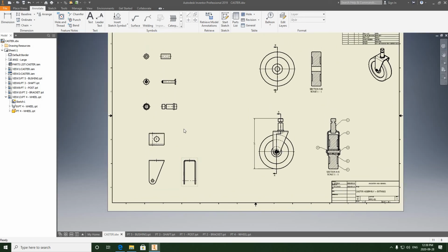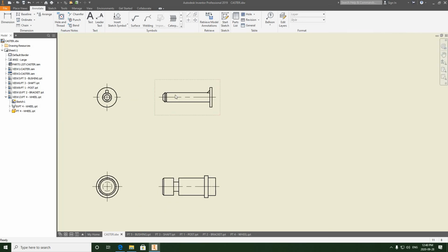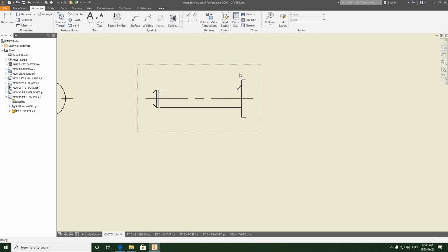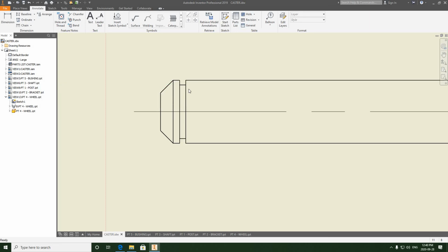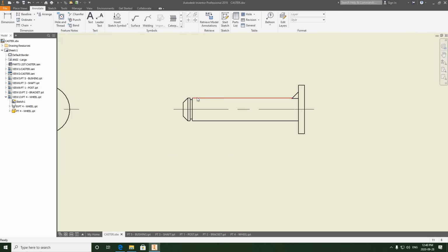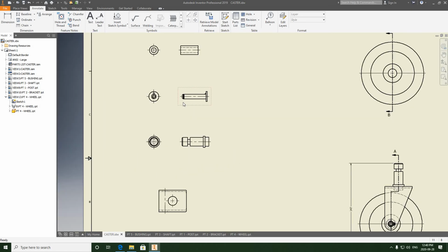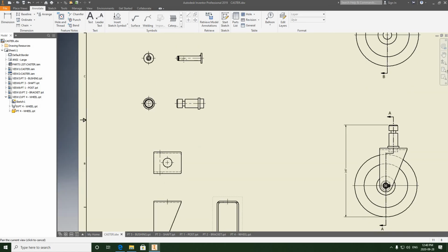Okay, before we close off for today, we're going to do something new with this drawing, something that we never did in Inventor in grade 11. Because this can be a bit of a difficult part to dimension everything. This is so small. Like these parts are small, and this has a lot of detail in a very confined amount of space. So what we're going to do is create a detail view of a couple of items, right?